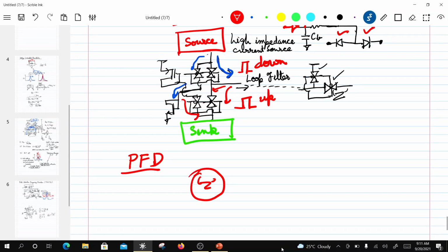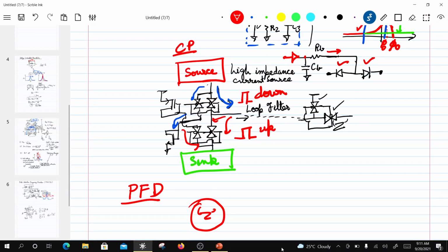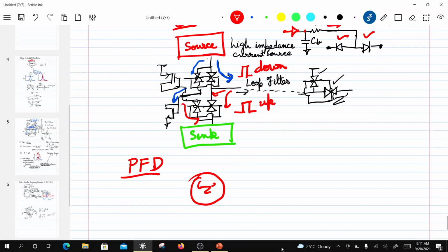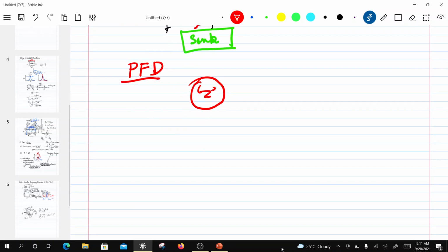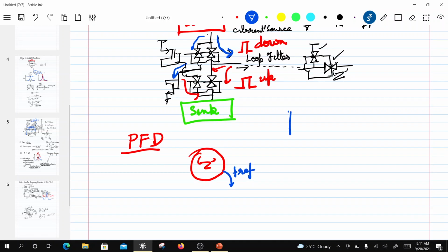So this is basically the high impedance state when the PLL is locked to the desired frequency, right? And let's say that I have FREF come first, okay, and FDIV. So let's say there are two inputs to a PFD. Okay, PFD has got two inputs. One is your FREF, which is coming from the crystal.